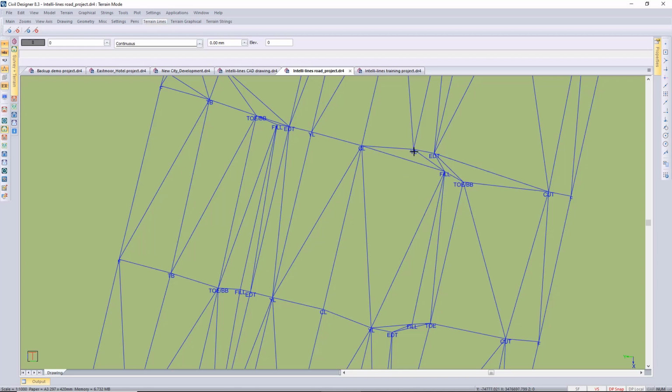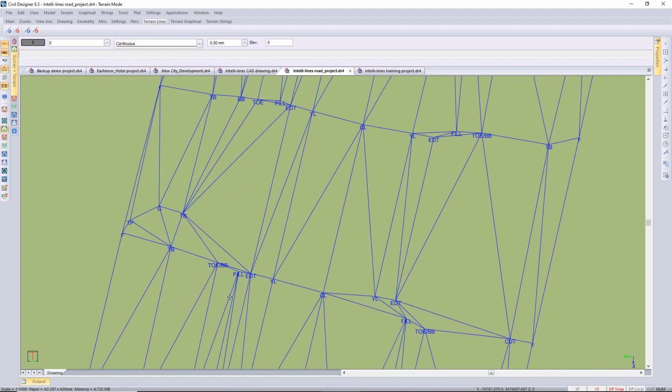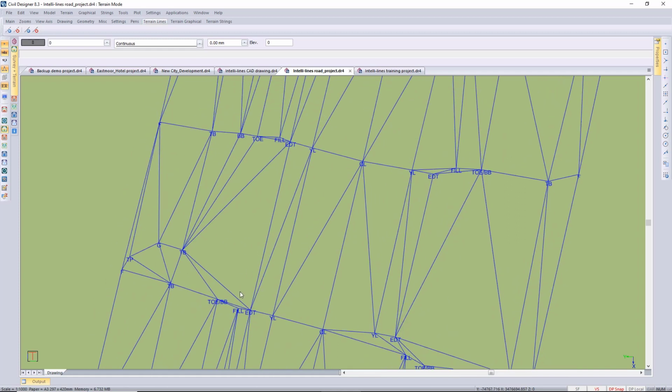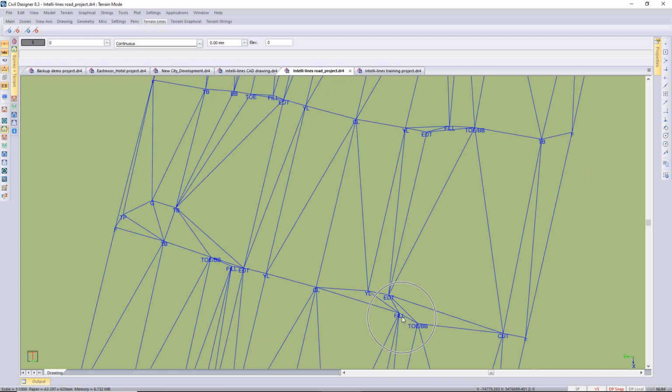And can you see that the normal triangulation hasn't joined up the edge of road to edge of road or yellow line to yellow line? So if you are working on a rehabilitation, you won't be getting the correct levels. So from full to full, you want those lines, for example, to be running straight through. Instead, it's connected the closest point when creating those triangles.